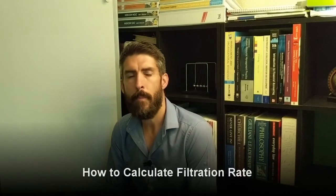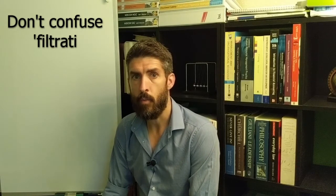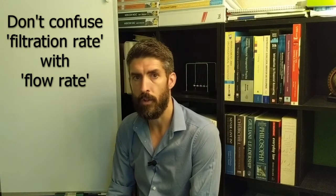In this video, I'm going to show you how to work out your system's filtration rate. What I mean by filtration rate is not the flow rate. I don't want you to get it confused with flow rate. The flow rate is the speed at which water is moving throughout the entire system, whereas filtration rate is the speed at which water is moving vertically downwards through the filters.